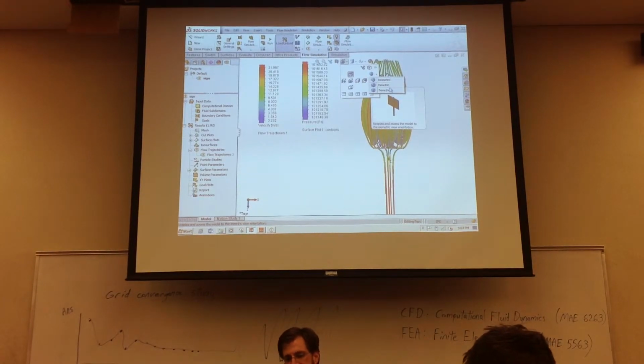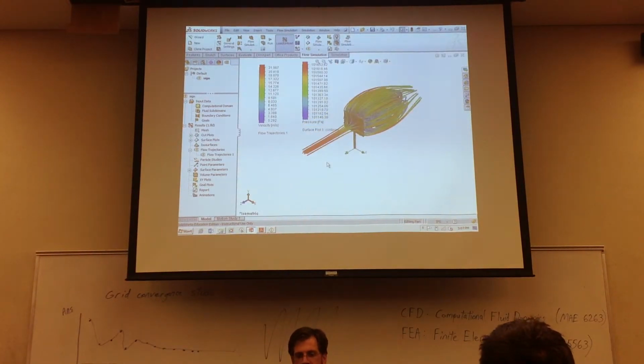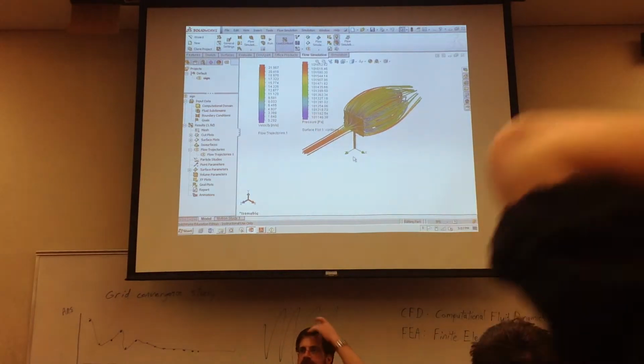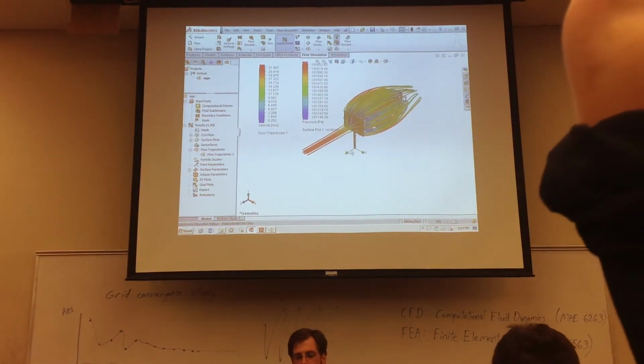The difference between them, honestly, just has to do with how the different orthogonal directions are represented in 2D space. Normally your X, Y, and Z directions are 90 degrees apart, right? Well, in a 2D representation, like an isometric, they're not 90 degrees apart. In this case, it may be like a 60-degree angle instead of a 90-degree angle on paper, if you measured it with a protractor.